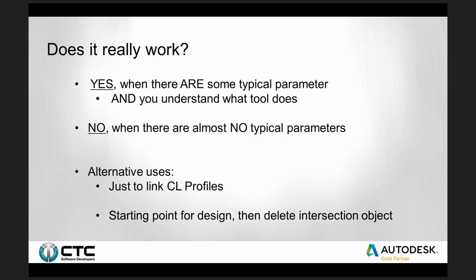You have to understand all the targets, all the baselines, all the regions and alignments and profiles that it's creating so that you can step back and say, well, in this road recon, we have to tie in over here. How do I handle that? If you know how the intersection tool is thinking, you'll be able to manage that.